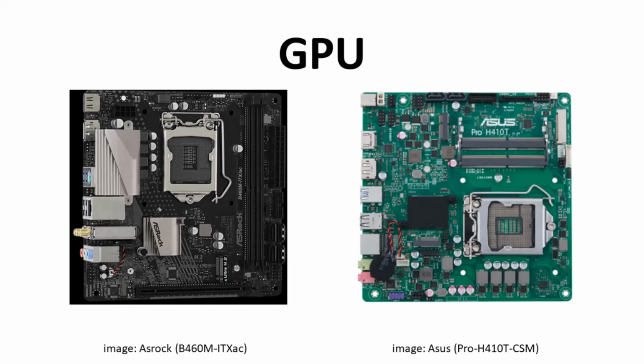Note that the thin board on the right has no PCIe slot. Actually, some thin boards do have a PCIe slot, but it normally has only 4 or maybe 8 lanes. If you read the board manual, it may also have very limited power output, like even just 25 watts. So options for an internal discrete GPU with a thin mini-ITX board are extremely limited. If you are aiming for a 45mm high case, then your options are down to just one option: integrated graphics. In this case, the GPU question really comes back to the CPU.